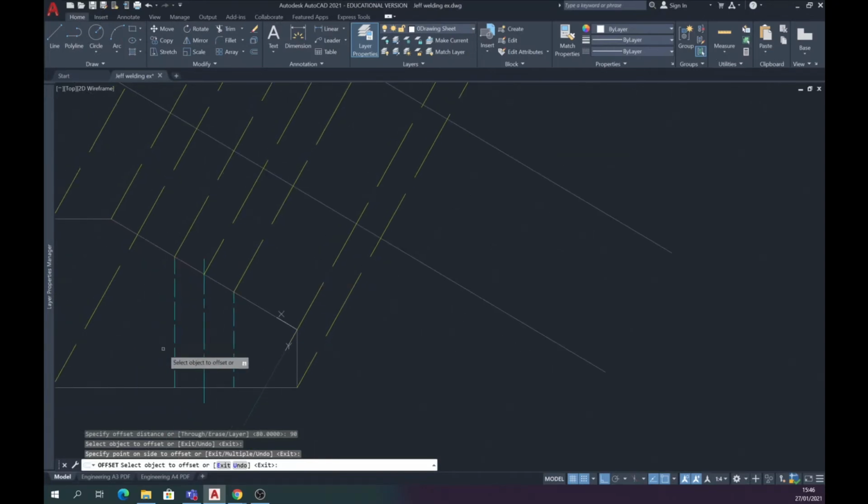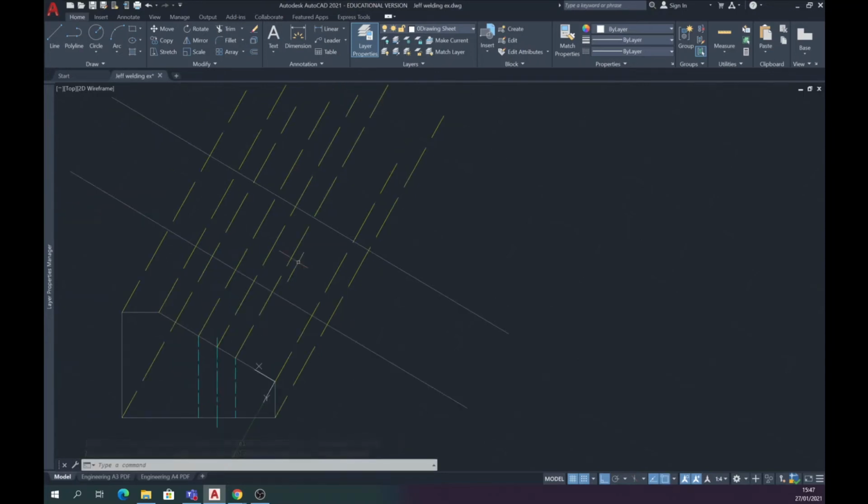Realistically, I have to make sure that I have enough width to have this circular feature, which is actually a borehole that travels down through that inclined plane, centered on this line and extending out to these two hidden detail lines. What I can do now is use the trim command, and I'm going to get rid of the excess parts of this drawing that we don't require.